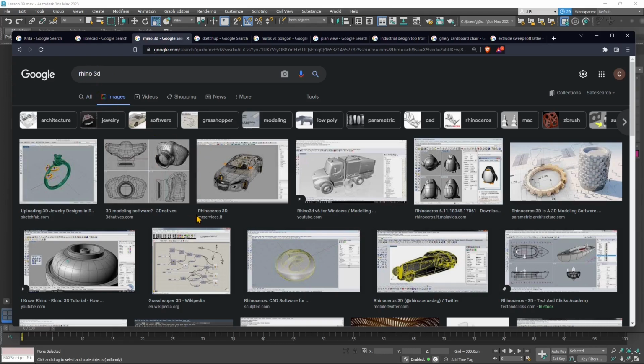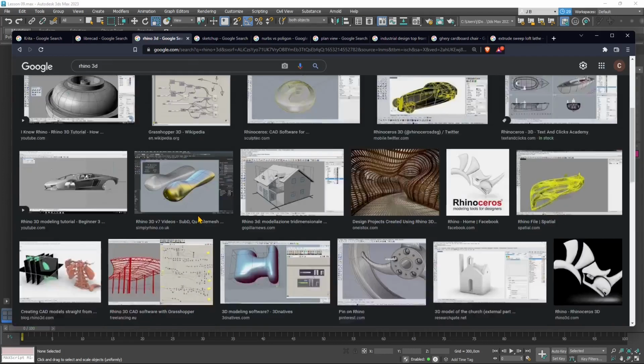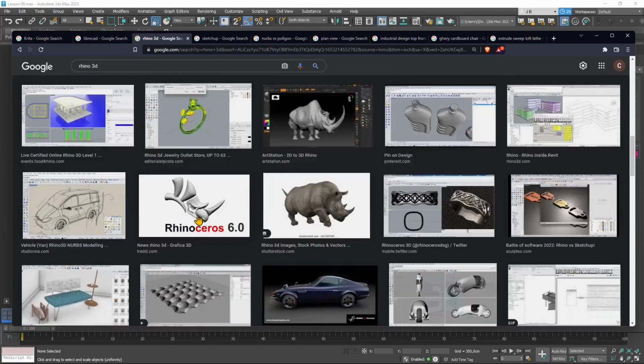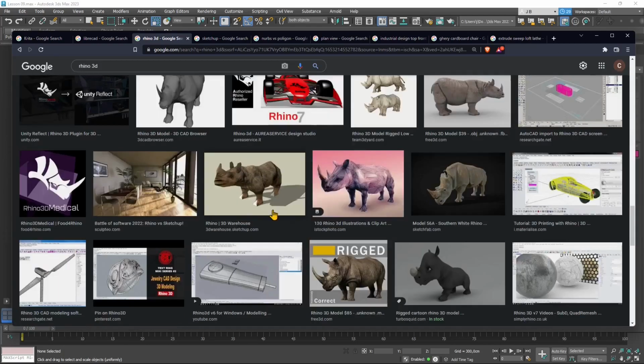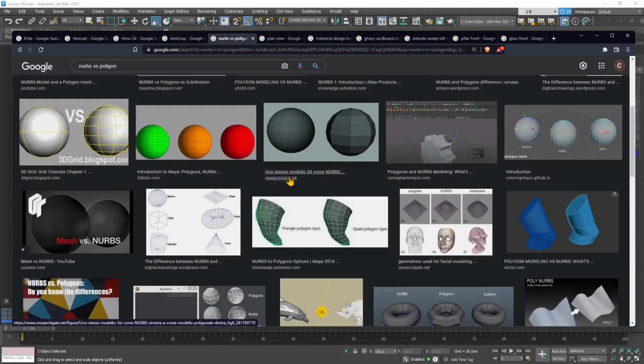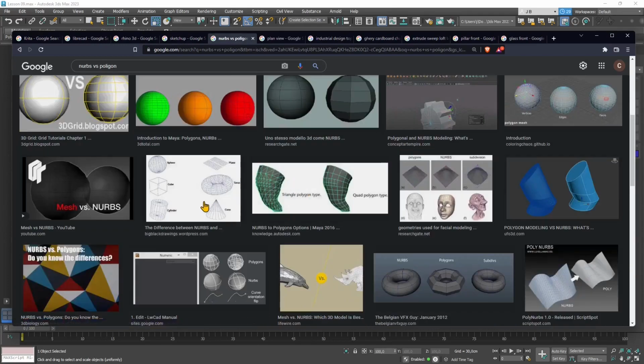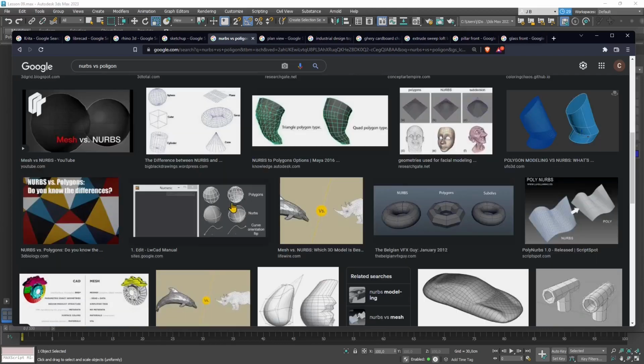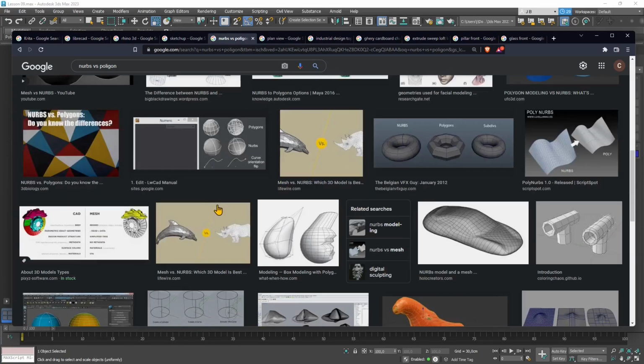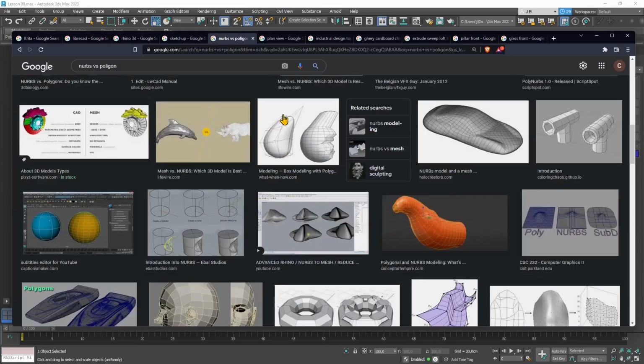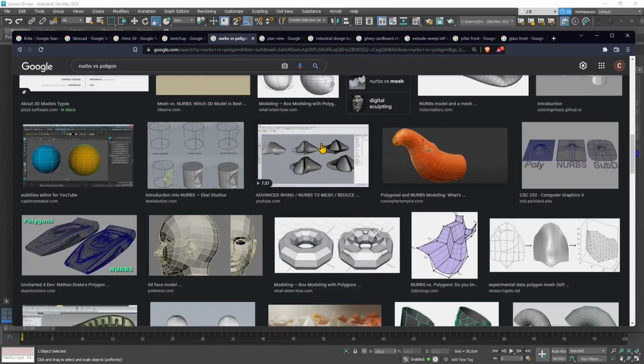For example, in Rhino 3D, which is a NURBS modeling tool, we find a lot of these tools here, and similar, like you have also 2-rail sweep, 1-rail sweep, and a lot of other tools that can convert simple curves into complex 3D surfaces, 3D shapes, and then you can also create solids out of those surfaces.